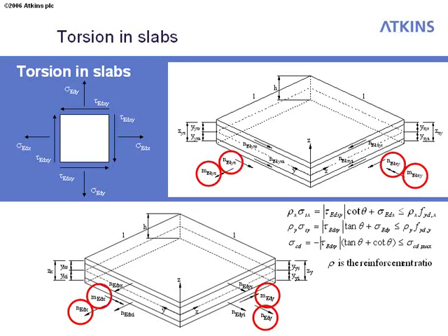It doesn't cover skew reinforcement because the rules were primarily drafted for analysing complicated structures, like weird-shaped box girders, where the reinforcement was still predominantly orthogonal, even though the overall shape was complex. It wasn't so much drafted for slabs, skew slabs, where the reinforcement is quite likely to be skewed.